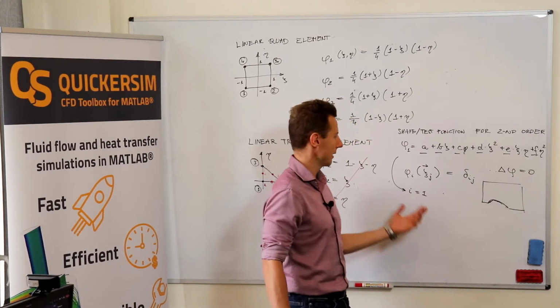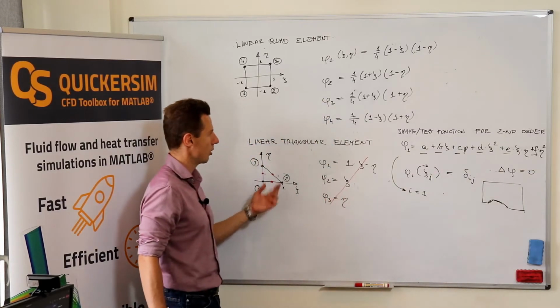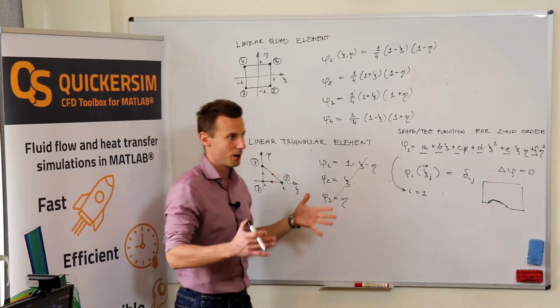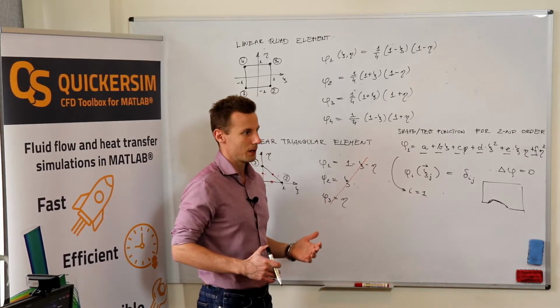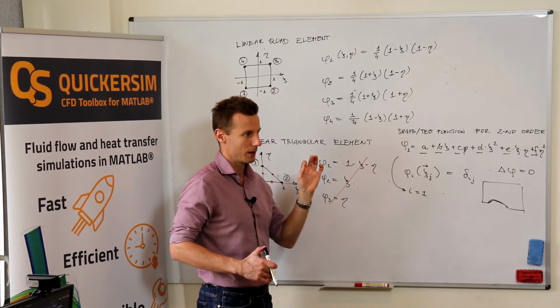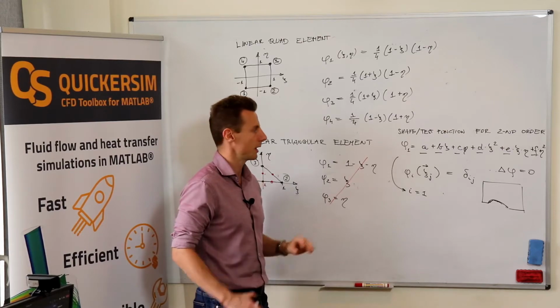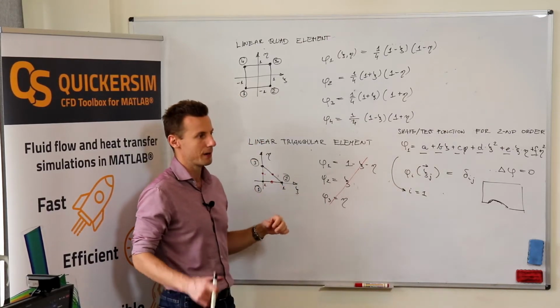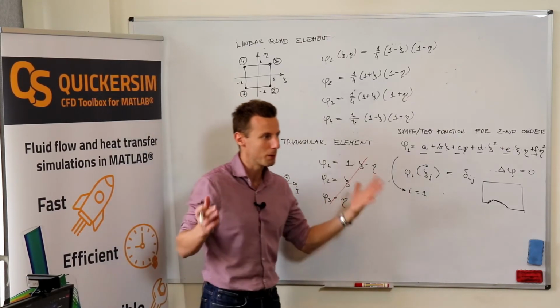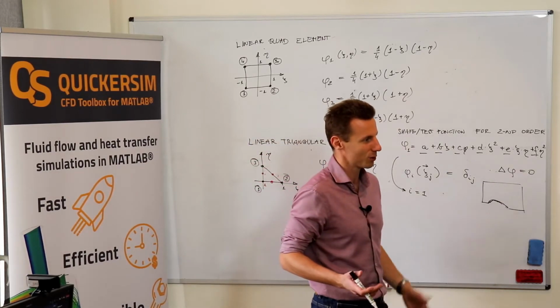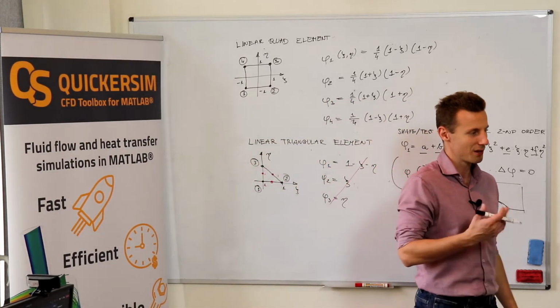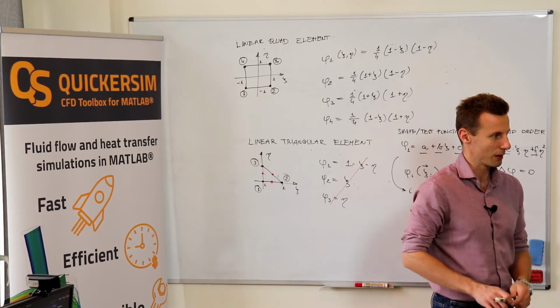The problem is that even for higher order methods, the local matrices become larger and larger, like the local matrices of the higher order element. Then your global matrix becomes more dense, not so sparse. So there are really trade-offs.